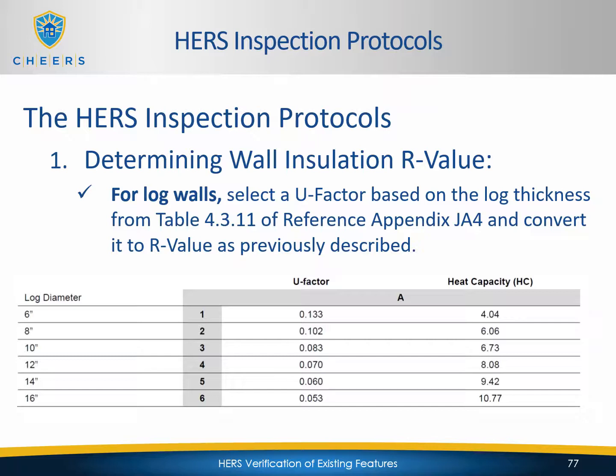For log walls, select a U factor based on the log thickness from Table 4.3.11 of Reference Appendix JA4 and convert it to R value as previously described. And this is the table that I just mentioned.